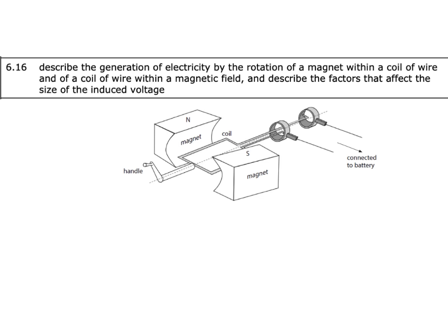voltage being induced. If we somehow managed to make a system where the magnet moved and the coil stayed in the same place, it would be the exact same procedure, as the field lines would still be being cut by the coil, and therefore a voltage would still be being induced. It would be the same principle if the magnet was moving instead of the coil.